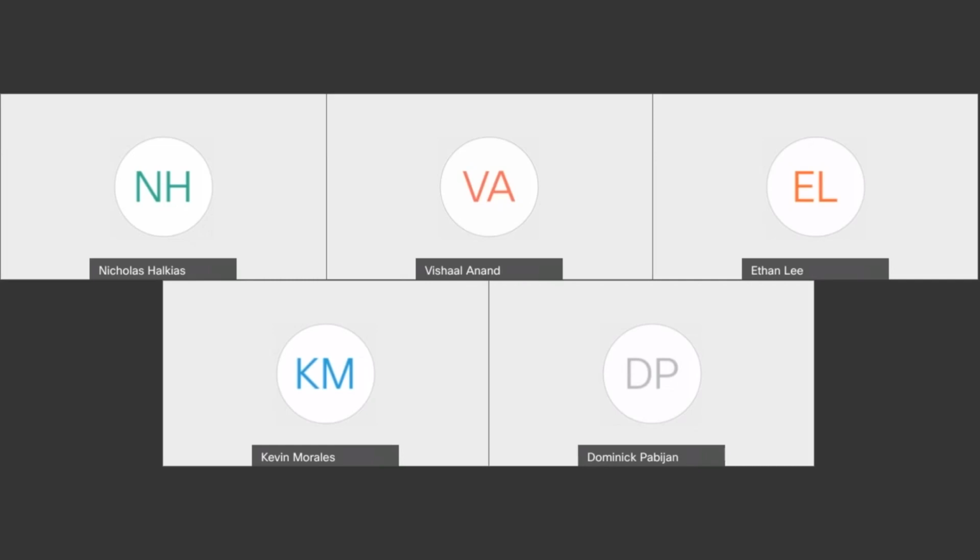Once you click on stress analysis, it'll make a whole new ribbon up here, and you just need to click create study, and then you just need to name what kind of analysis you're doing. If you want to do different pressures, different forces, different orientations, you can name it all different things. You can have 10 different studies all going on at once. And you just need to click OK after naming it.